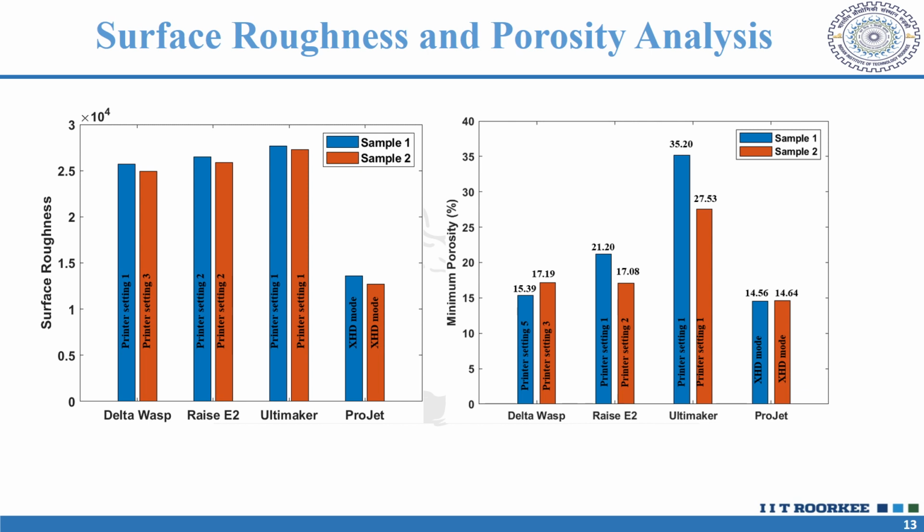We determined the roughness and porosity in different slices using MATLAB code. What we define as surface roughness is the deviation from the actual dimension of the object, that is there is some error in the dimension of the sample printed, and there are voids apart from the inserted voids. First is showing the surface roughness plot. Second is presenting the porosity in different samples.